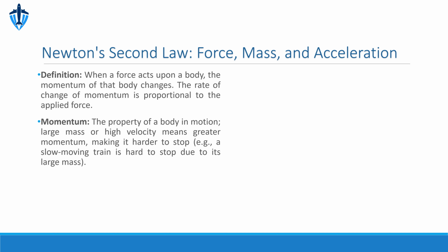Let's analyze a specific example using the spur gear shown. Imagine the larger, blue, 12-inch diameter gear is driving the smaller, yellow, 9-inch diameter gear. When we look at the mechanical advantage in terms of force, we divide the effort arm, the driven gear's diameter, by the resistance arm, the drive gear's diameter. This gives us a ratio of 9 divided by 12, or 0.75. This is a fractional disadvantage, meaning the output force will be less than the input force.